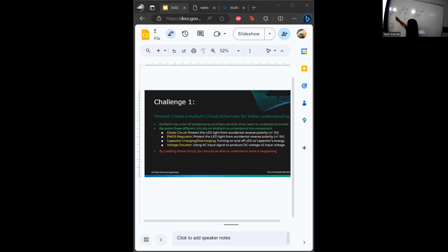So if we put in 5 volts, your output will double, but not really, it comes out to be 8.6. If these diodes did not have the 0.7 drop, there would be exactly 10 volts, right? Because the only reason why this is 8.6 and not 10 is because of all these voltages you have to take out, right? So this is one cycle. So through one cycle, you should be able to go from 5 volts to 8.6 volts.